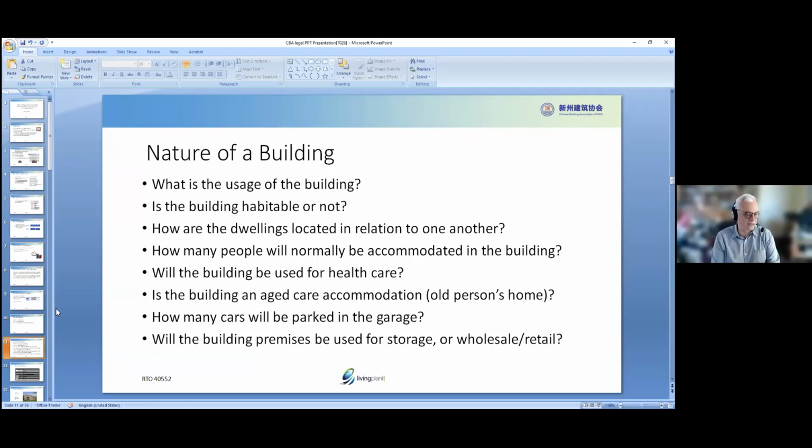It's like this COVID thing now, where they're saying only 1 person per 4 square meters, right? Well, the Building Code of Australia has that rule for every type of building. It will tell you that in a bar, you're allowed to have 2 people for every square meter. But in a retail shop, you need 3 square meters for every 1 person in a retail shop. So these are rules that are in the building code. We just don't do what we like. We have to follow certain requirements.